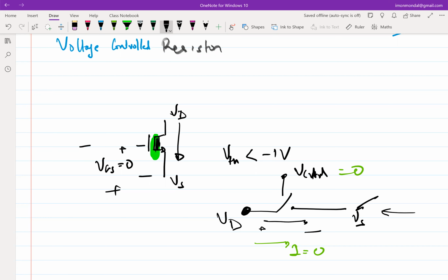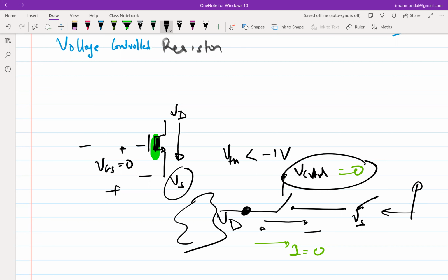So let's assume that I set V control to 0, right? And I want to turn the MOSFET off. Then what should I do? I have to increase VS, right? Fine, MOSFET is turned off, but then what happens? You have some logic connected to VD, some network connected to VD. However, now you would want to also have some network connected to VS also, because more options, right? You would want to have access to both these terminals. But because you are using VS to turn off and on your MOSFET, you are limiting your options.